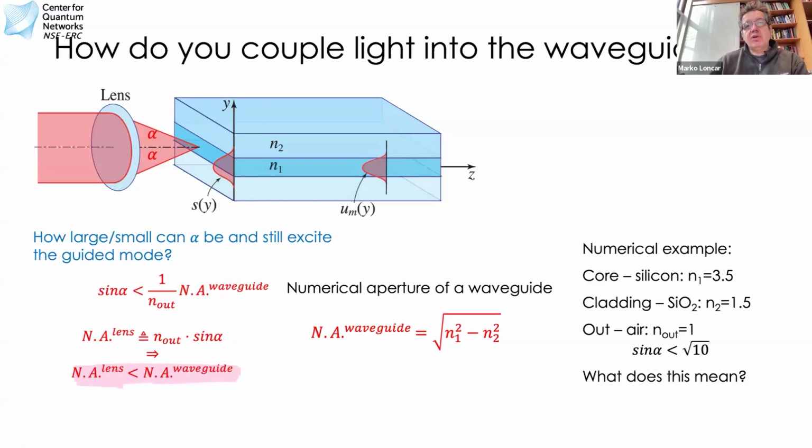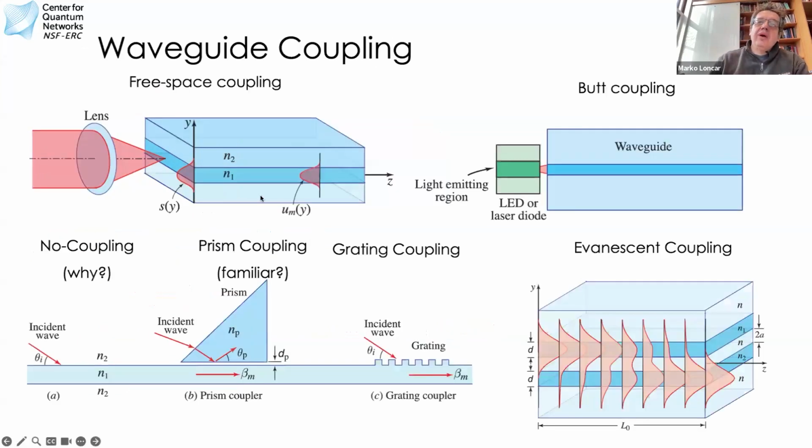which is a very, very convenient way of doing it. Other ways, in addition to this kind of lens coupling or tapered fiber coupling that you can use to bring light in, is the so-called butt coupling technique, where it's particularly good if you want to bring light directly from the laser or some other waveguide that has similar mode diameter, similar cross-section to the waveguide you're considering. So, for example, if the laser diameter is maybe a micron across or something like that, that actually can couple very nicely to the waveguide, properly designed, even without any lens in between.